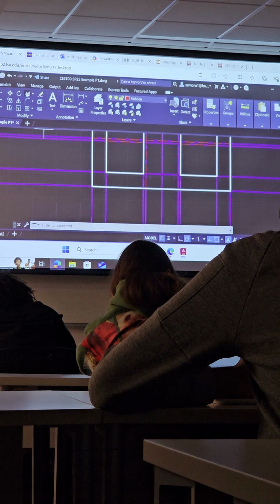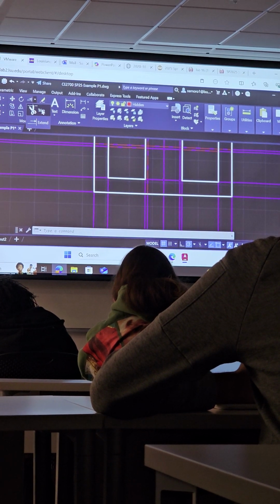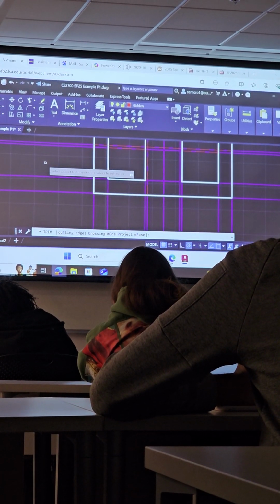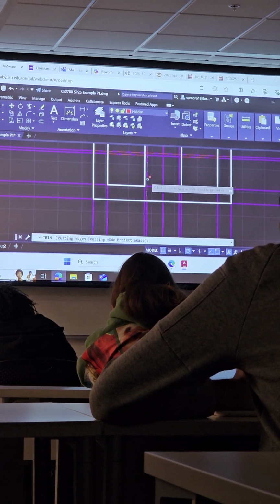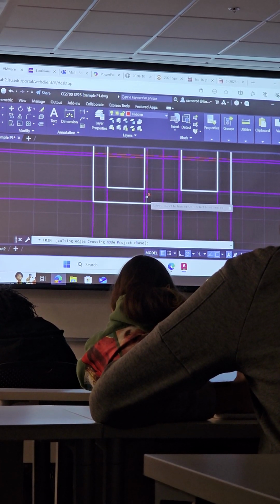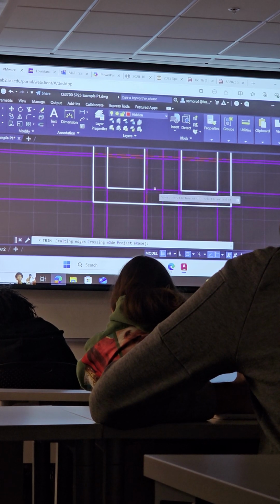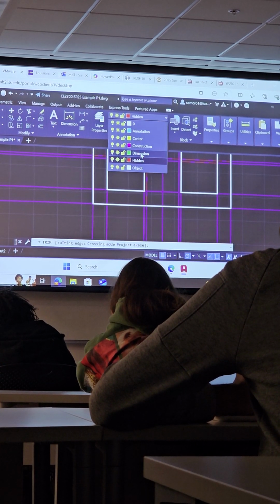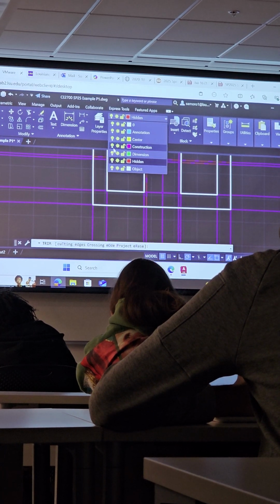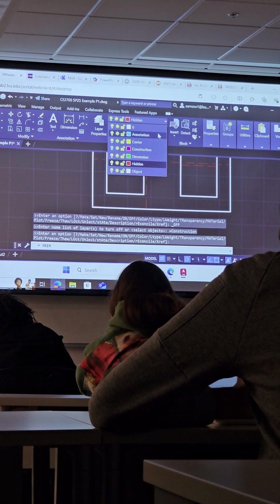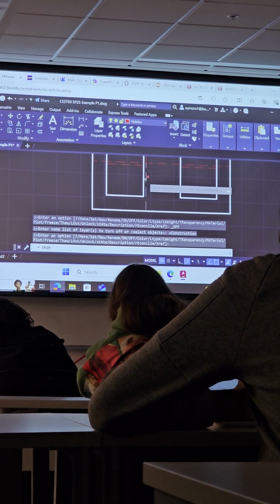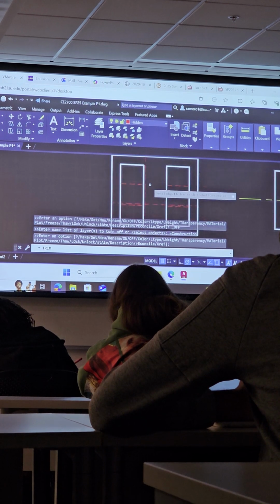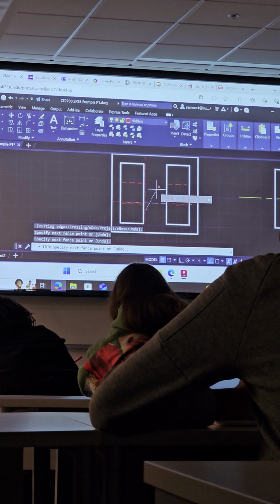So that gives me an opportunity to show you guys the trim command. If I invoke the trim command, it says select the object to trim. So I want to trim... it's not picking it up. I need to turn off the construction line here. Oh, then I lose my trim edge. Oh, no, I don't. So I can use the trim command to trim this line back.